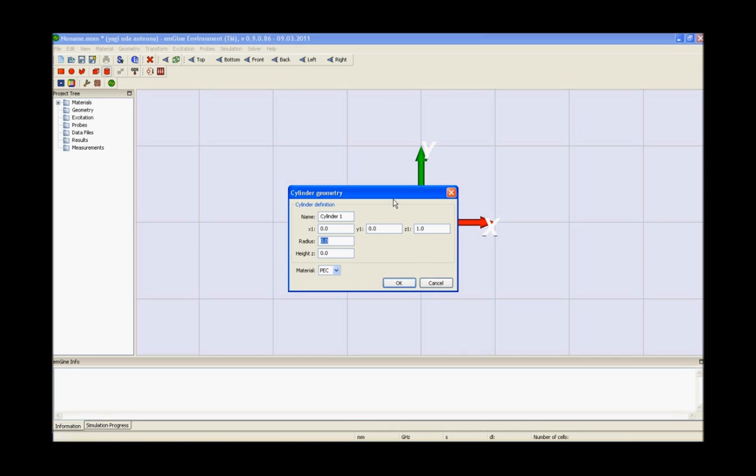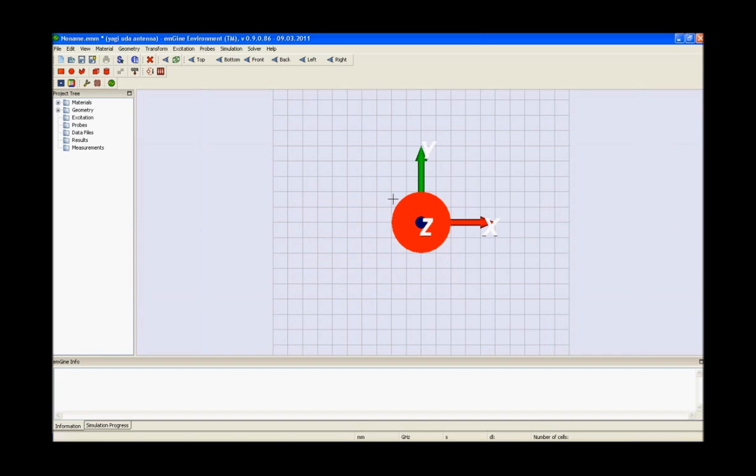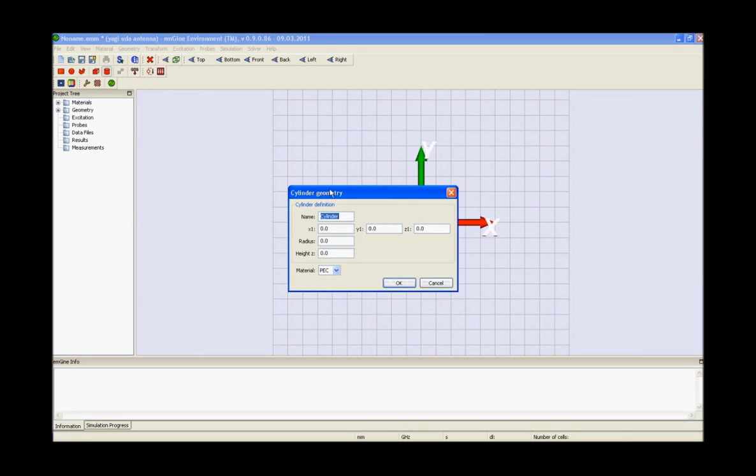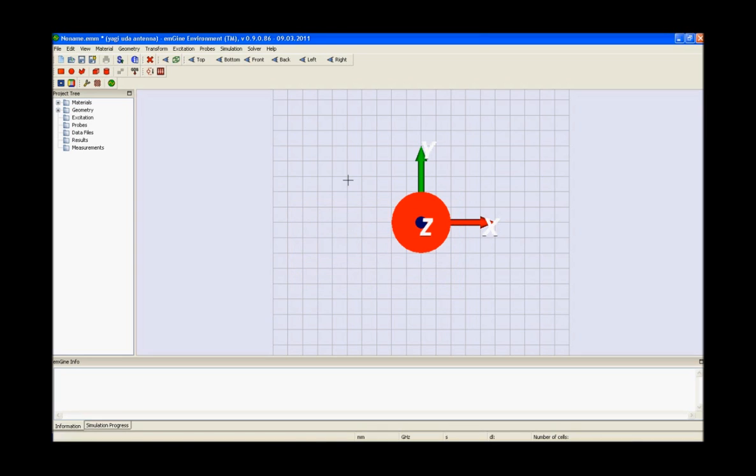The next step is to design a driven element of cylinder for modeling of wire-type Yagi Uda antenna. This can be easily achieved by creating a cylinder made up of PEC material. Since Yagi Uda antenna is a straight collinear wire with a small space between them, hence we need to design the other part of the antenna also. Again, repeat the same process and press OK.